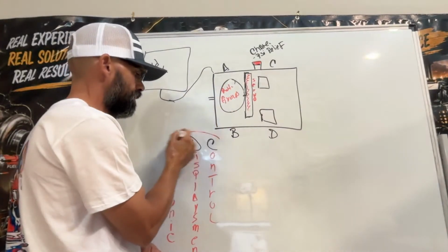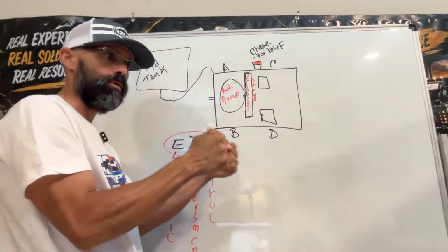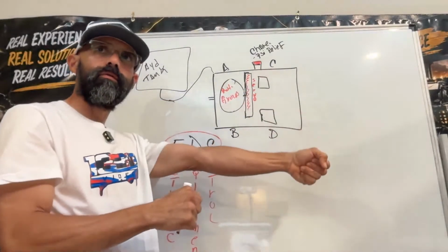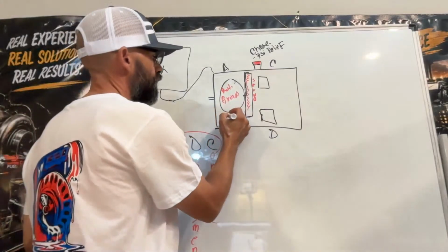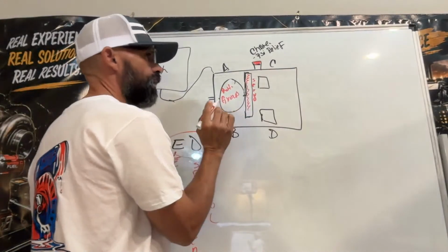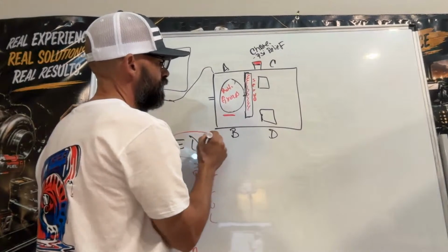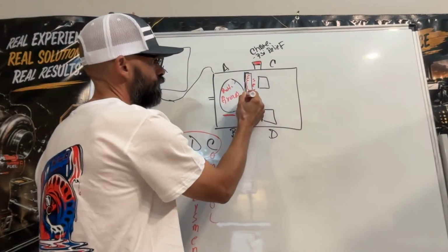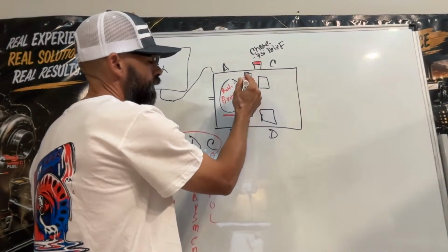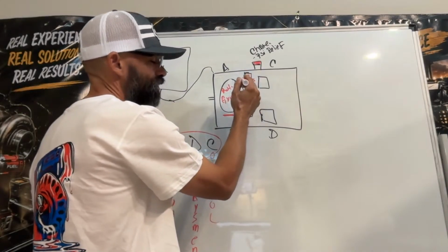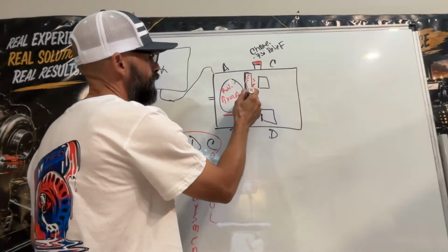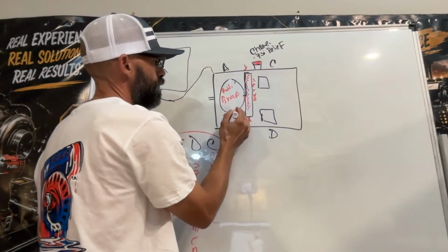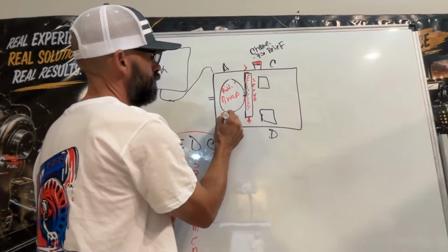They don't have EDCs. From the joystick, there's a cable going down to the pump, and as you go forward or reverse, the swash plate is going to move. It goes to neutral position like that, and then the swash plate, depending on the servo movement, goes either this direction or this direction. With no direction, the swash plate is neutral, like that.